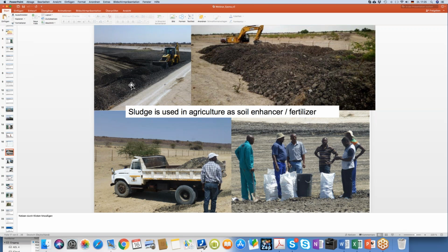So the question is how to take the sludge off, and this is what we try to do with either microscreening, which is quite effective, as we have seen, or this UASB. There may be other methods like Imhoff tanks or whatever, but these two have been selected because we see all over the world there are so many wastewater stabilization ponds, and all of them have problems.